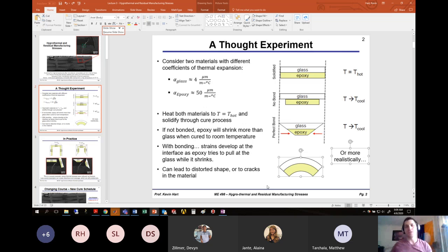Okay, so we're going to talk about how that curvature and how that math works for our laminates, right? That may have many different layers, which themselves have different coefficients of thermal expansion in different directions. Also, the materials that make up those lamina, carbon fibers, may also have different coefficients of thermal expansion in different directions. A single fiber itself. Complicated, man. So all of these things contribute to these residual strains and curvatures that might happen inside of a laminate from the cool down process, because its unstressed and unstrained state is this high temperature at which we fabricated the piece.